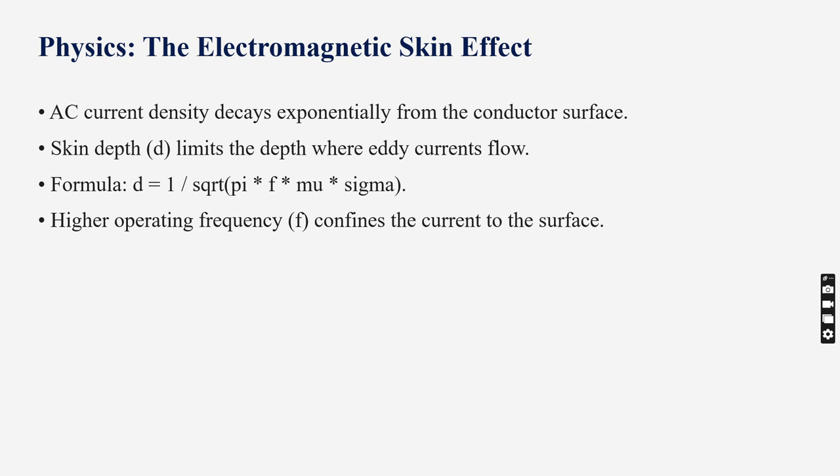The skin depth is inversely proportional to the square root of operational frequency, electrical conductivity, and magnetic permeability. Because carbon steel is both highly conductive and highly permeable, eddy currents are confined to an extremely thin surface layer.